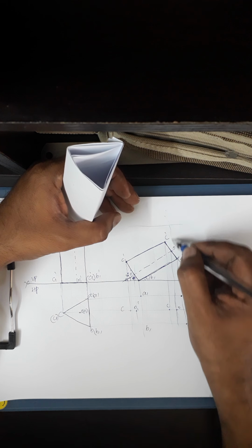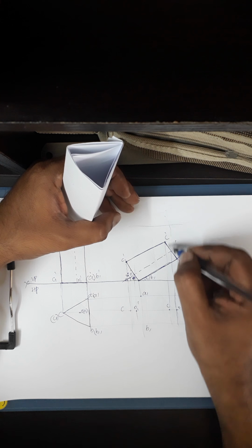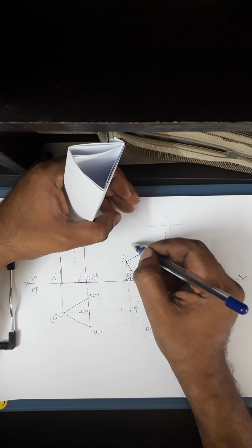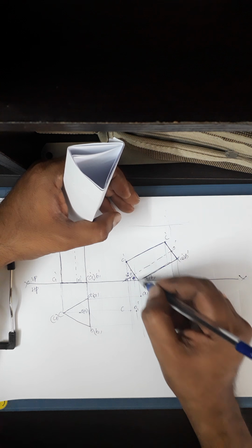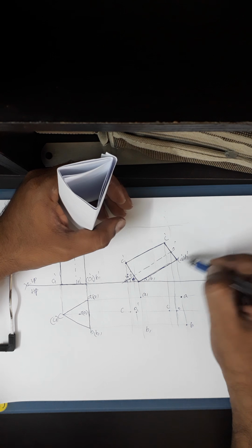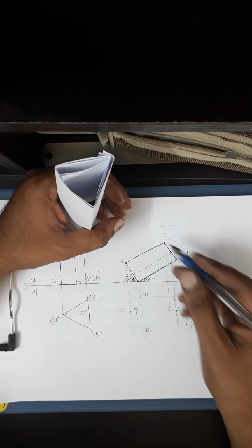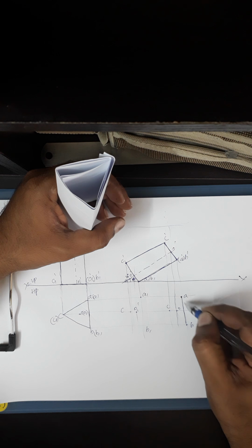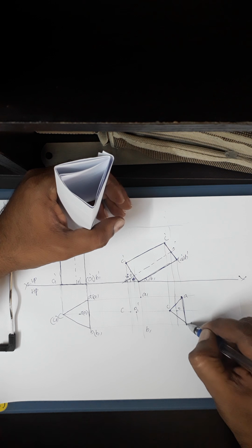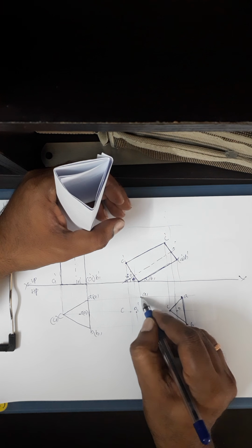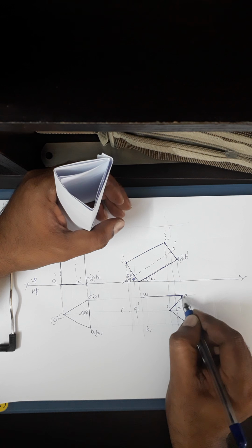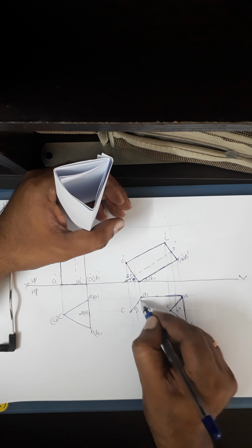Or you can see the complete end face by drawing lines perpendicular to the XY line. You can see this end face, but not this. You have to pass through the solid to see this face, right? So in that case, if the end face which is nearer to VP is the top end face, complete all the edges of that end face with a thick continuous line. So all edges are visible. Then you go for the outermost edges. All outermost edges are visible, so complete all edges with a thick continuous line.